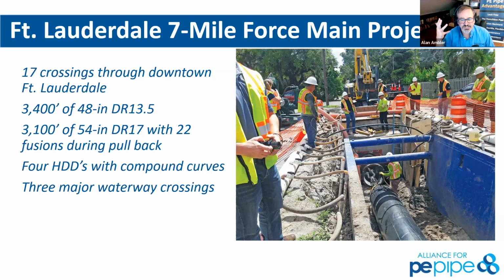In many places, in dense urban areas where we've built and rebuilt, and also dug canals and installed things, we're going to look for steel sheet pile that may very well hold the foundation of the bridge in that canal crossing. Those are some of the things that we want to ask about in data collection.